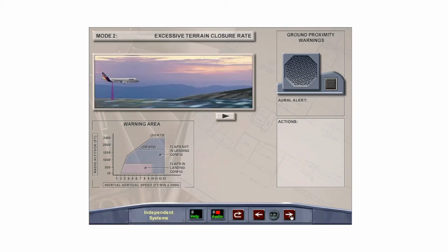As the aircraft enters the boundary, the GPWS light will illuminate, accompanied by an oral alert of terrain repeated twice, changing to a repetitive whoop-whoop pull-up, which will continue until the aircraft leaves the warning envelope.